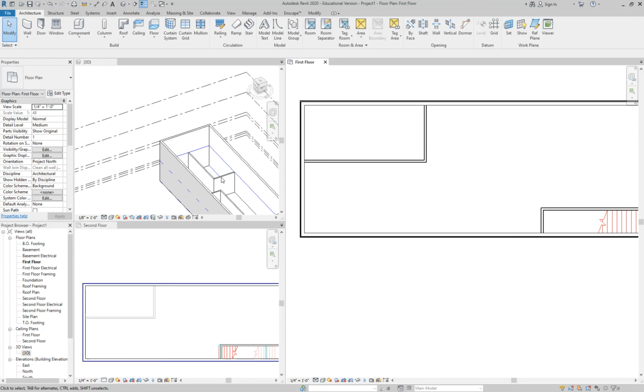You definitely want floors in here, so you'll have to work with your levels a little bit. Make sure you have a floor so that when you're on the 2nd floor, you don't look down into your 1st floor, and it doesn't look like everything's suspended in the air. I hope that's enough to at least get you started. You can start tracing around.